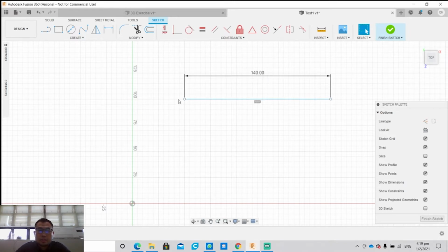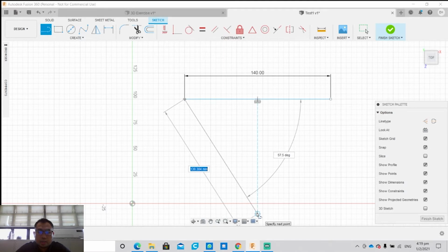So next I am going to create the triangle. I would like it to be much wider, sharper. So I'm going to create, as you can see, there is the dotted construction line. It tells you that that is the midpoint between those two lines. So I'm going to create the tip at the midpoint, the tip of the shovel at the midpoint.